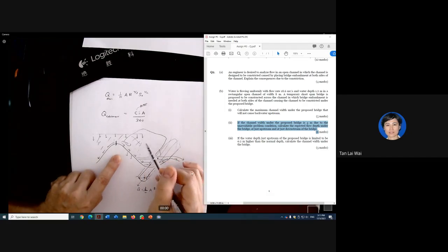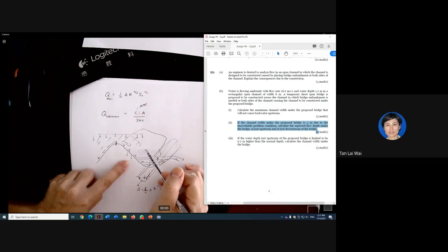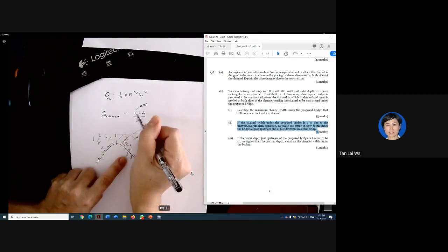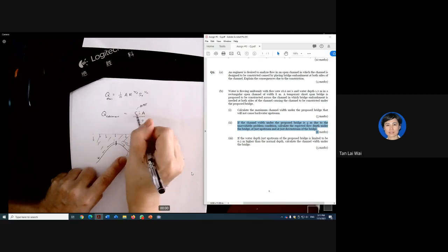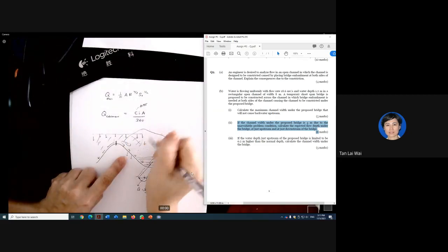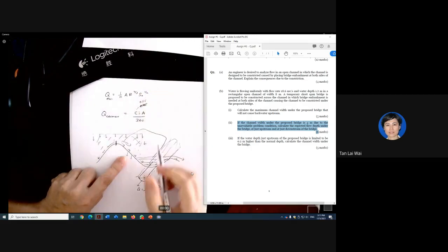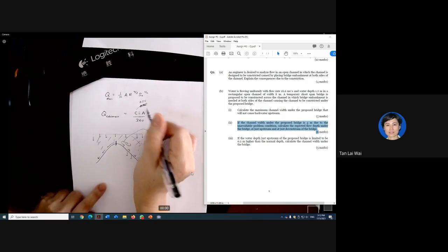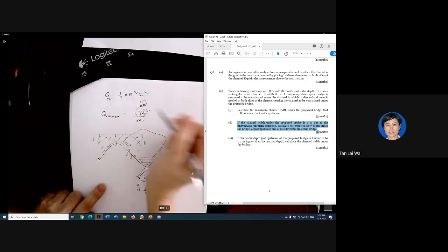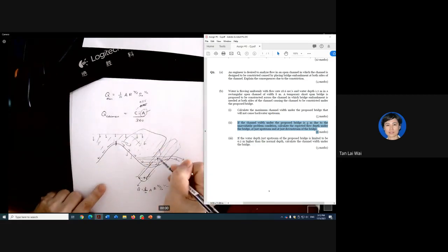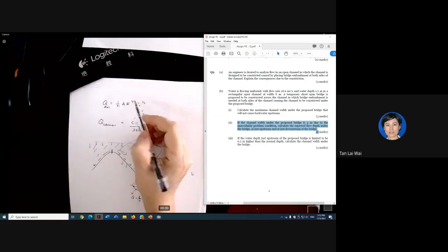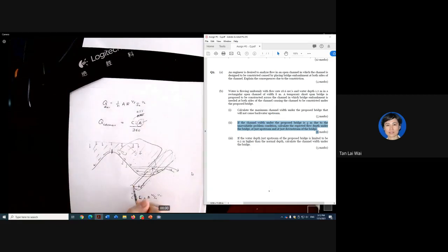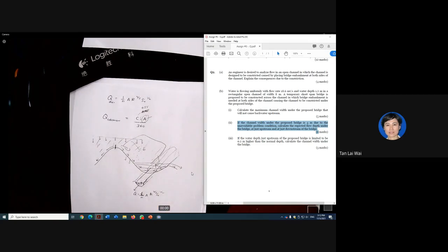Even if it's paved, you are going to get some water stuck in some depression or things like that. So normally this C is less than 1. If this is grass, you are going to get values such as 0.55 and things like that. That means less water going into this drain. So if you ask me what is this A, this A would be the area draining into this drain. And what would this A be? This A is this flow area in the drain. So far, Indrajit, are you clear about this?